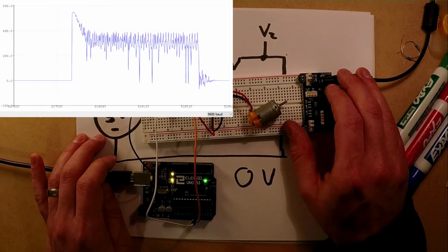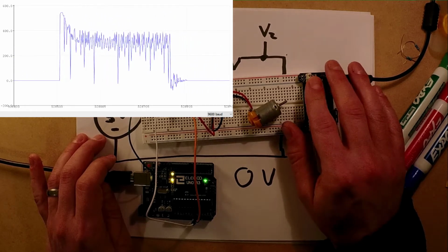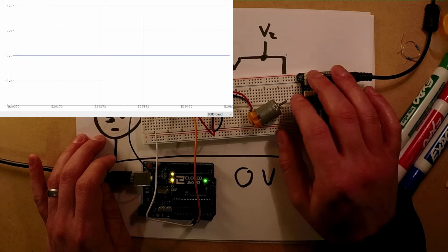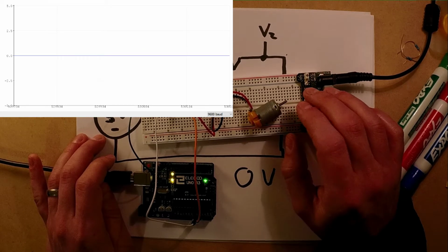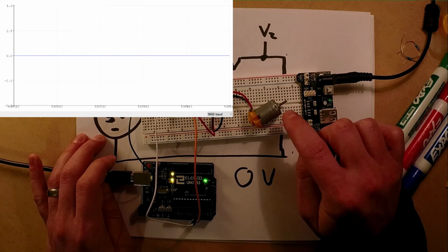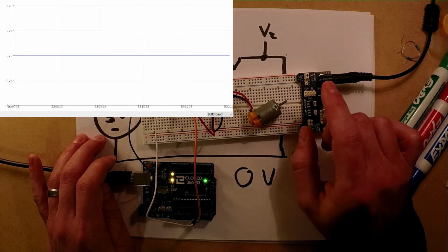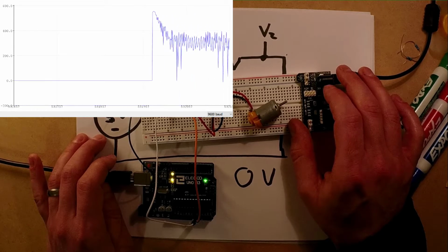So what you're seeing there is actually what we call back EMF or flyback voltage. You'll learn more about this in the transistor activity, but this is an effect that happens when you turn off something like a motor that's got a large inductance to it, as it tends to send current backwards through your circuit.